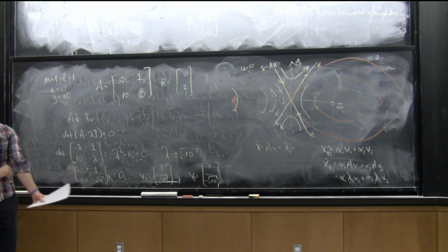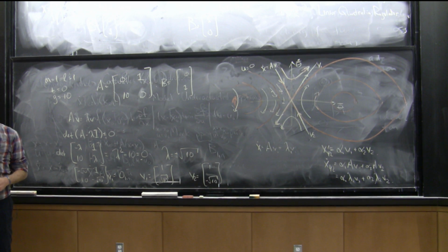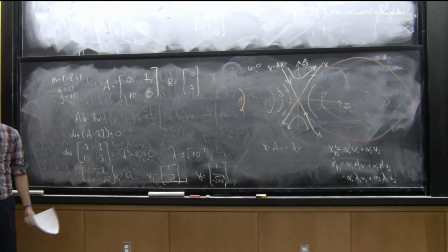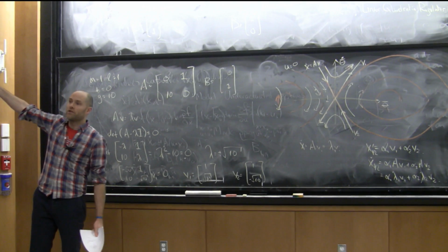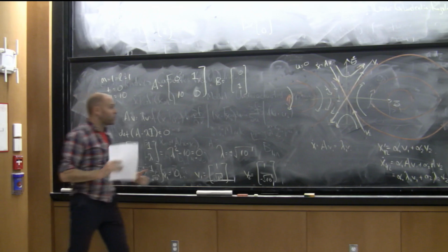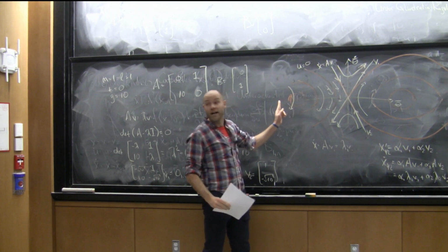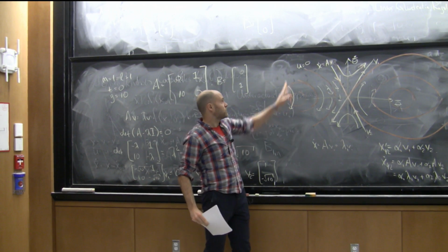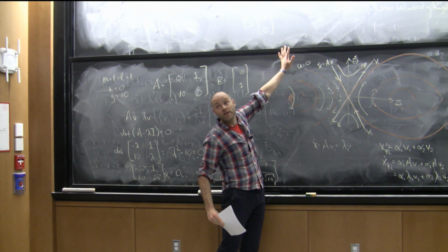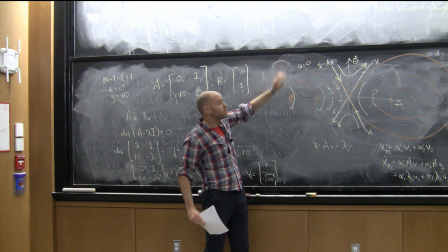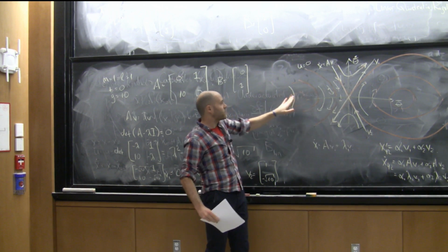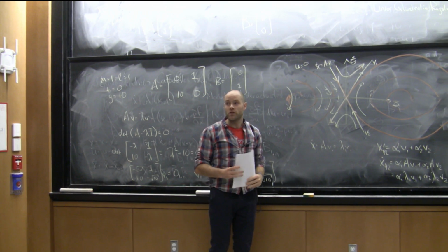Yeah? Did feedback linearization just turn some of that over there into a fixed point? Maybe. It depends if you have enough torque, right? If you're over here, you can only have fixed points along the line, first of all. So there is a fundamental thing you can't do up there because you've got velocity. But anywhere around here, if you have enough torque, you could combine those things.